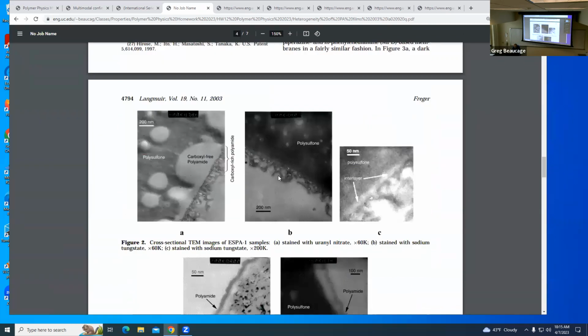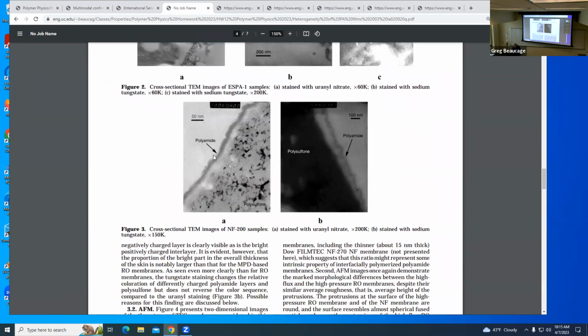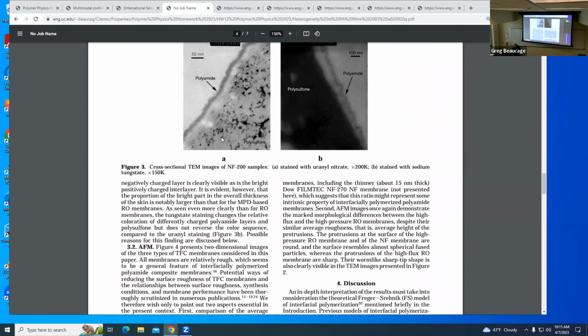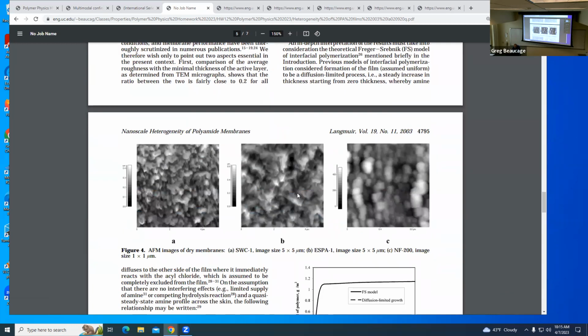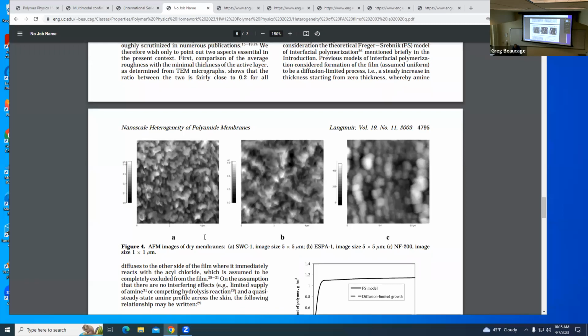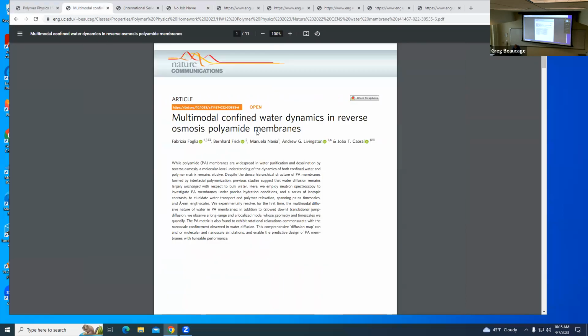So they show that there's not much you can say, but basically it's not clean, right? There's a lot of, you could say, aggregates, and then there are pores. He's looking just at that black layer; the polysulfone's down here. With the polysulfone, the water just goes straight through, right? It's 50 nanometer, but still the water can go through that thing. So this is a really thin separation layer, and you can see clusters and different stuff in there, right? So our guy looks at that and says,